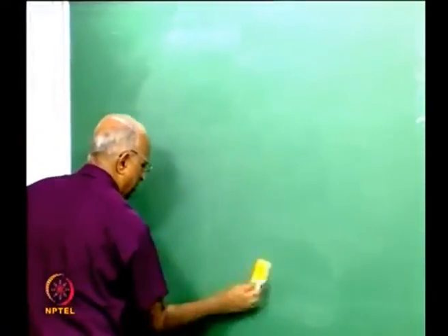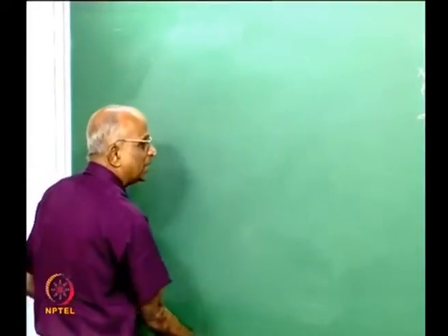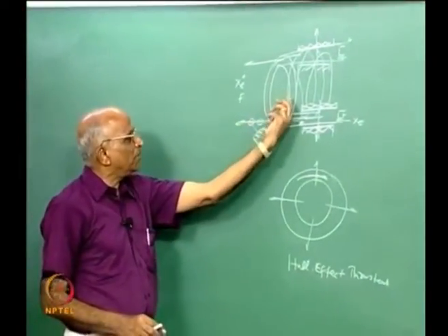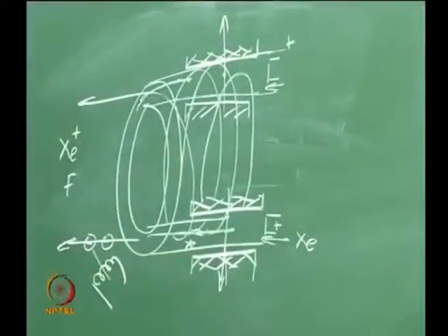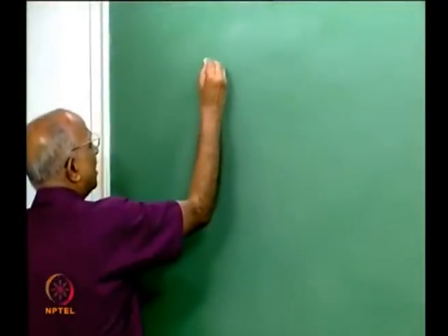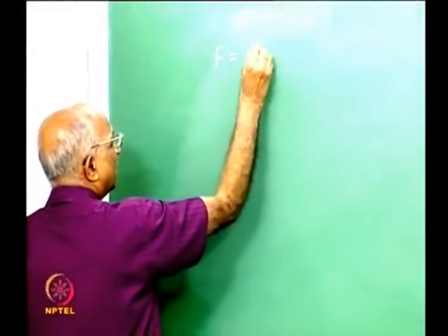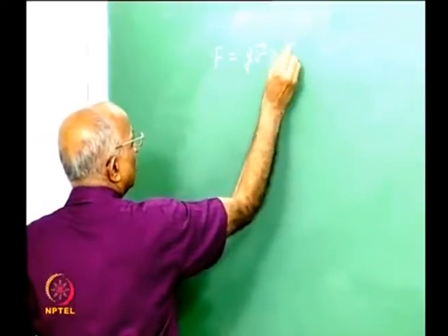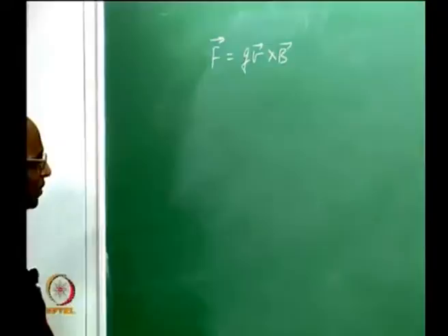In the electromagnetic principle things were small, and whenever we are studying all this we are not looking at the description of a thruster, but at the operation mechanism so that we can work out some numbers and also design one. Therefore, we said a force can also be generated in a magnetic field when a charge moves at a value of velocity. This is the force which we call the Lorentz equation.